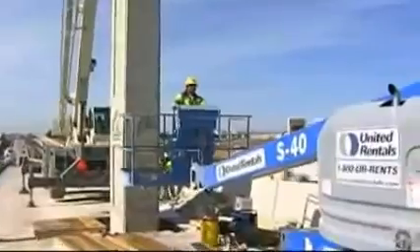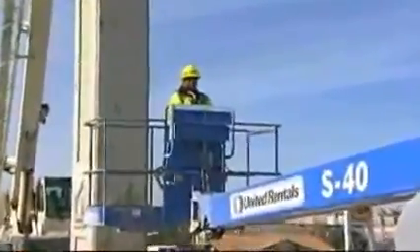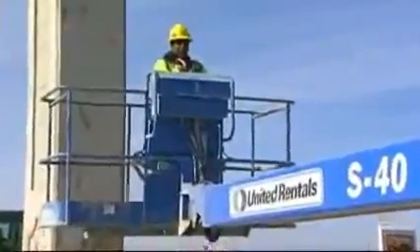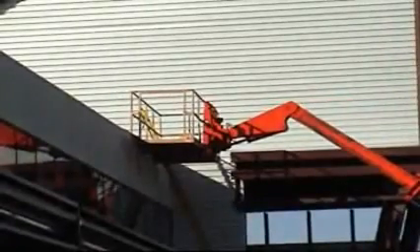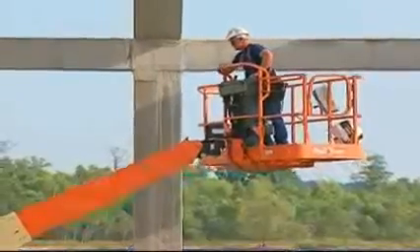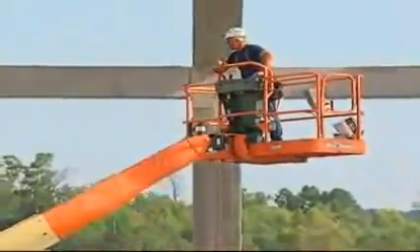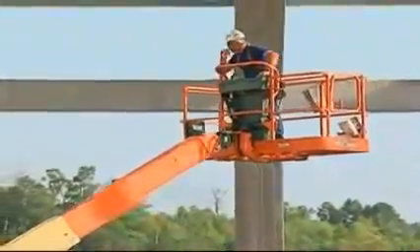Aerial lifts include several types of vehicle-mounted aerial devices used to elevate employees to job sites above ground. An extensible boom platform uses a single arm to lift a platform to the desired height, often by hydraulics or, less frequently, pneumatic pressure. The length of the arm limits the reach of the boom lift. Some boom lifts can extend the reach by using telescoping sections within the arm.